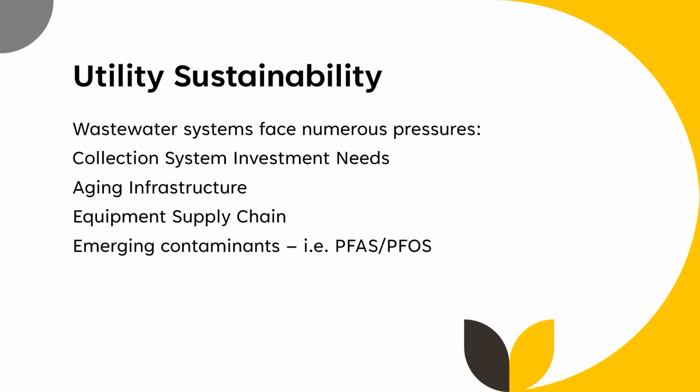Then we have a lot of, I don't know what's going to happen here, emerging contaminants. Primarily, the focus right now seems to be on PFAS and PFOS. Those are in your wastewater treatment plant biosolids right now. There's one state in the country that has banned land application, which is Maine. I spent a week earlier this year in New Hampshire, and believe me, that got everybody's attention there. Maine facilities anecdotally are reporting about three times higher cost for biosolids as a result of a ban on land application, because they're trucking it to out-of-state landfills at this point.